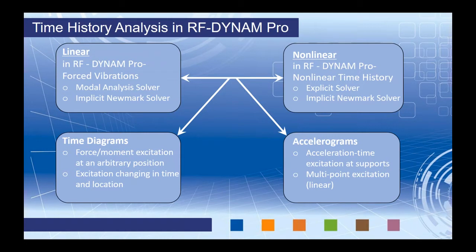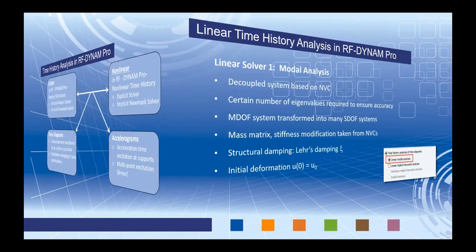Now, regardless of whether you're running a time diagram or an accelerogram, the display of results is available on a time course monitor, and this is certainly something that we'll be taking a look at quite a bit today. We can export the results into load cases for single time steps, so you can actually see the response of your structure at each individual time step back in RFEM, or we can export a result combination for the result envelope.